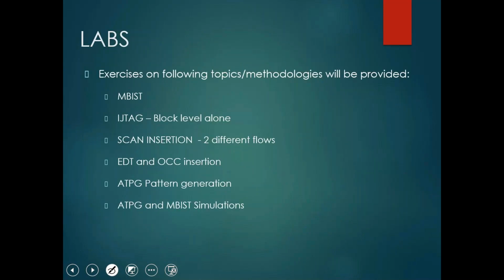The labs, whatever we have discussed in the course outline: memory-based testing, the JTAG, and JTAG here stands for Joint Test Action Group. It is a protocol actually. The Joint Test Action Group introduced a protocol that can be used for testing the inputs and outputs. Likewise, scan insertion also we will see. This is called compression, and this OCC is the clock control unit, what we have seen. And this is the ATPG, the test pattern generation concept.